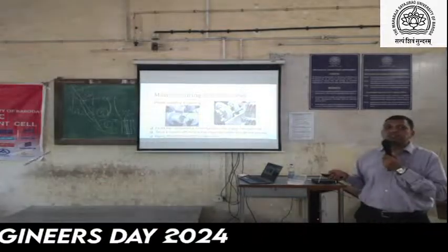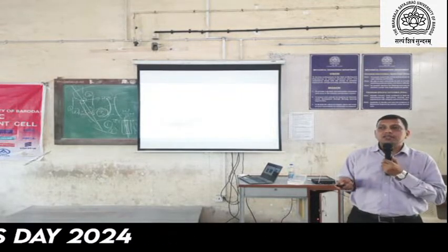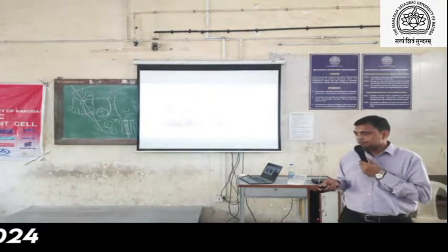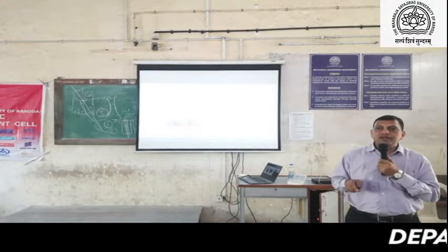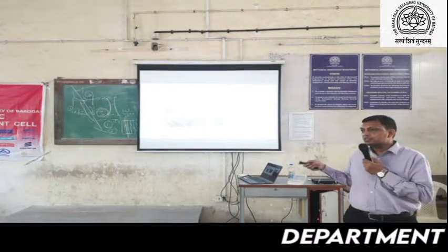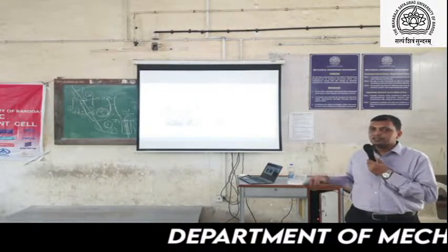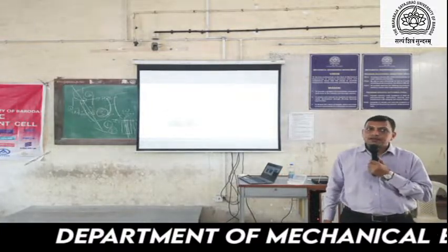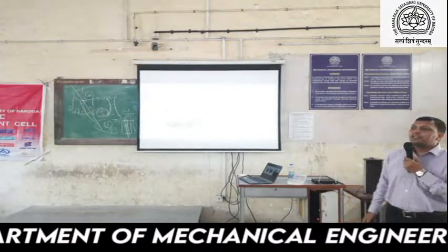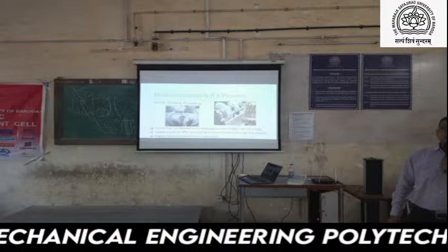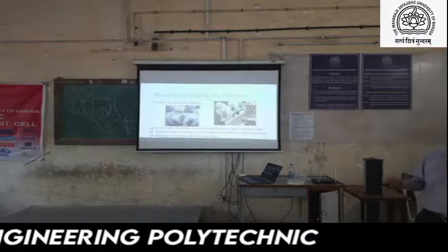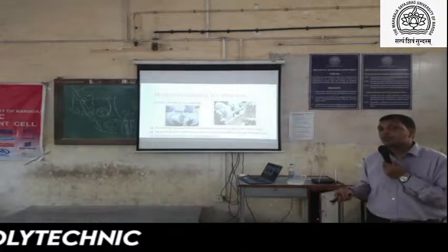In the grinding operation, there are different accuracy classes, which are defined by the accuracy of the pinions or the wheel. In low speed applications, we normally consider class 6 to 7.